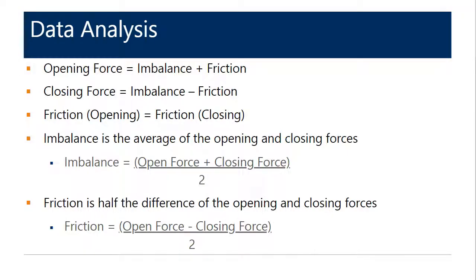So AASHTO calls for the bridge machinery to drive the span into its seats and for the brakes to apply and to hold that seating torque. So stability issues could arise if the control system is not sequenced correctly.